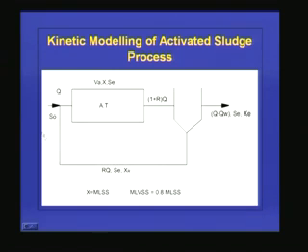solids, because sometimes along with the wastewater, the solids, along with organic solids, inorganic solids also will be there. So, this MLSS will be containing organic and inorganic solids, but if you want to find out what is exactly the microbial concentration, then we have to go for MLVSS, and many studies have shown that the ratio of MLSS and MLVSS is like this. If you have the MLSS value, if you multiply by 0.8, that is MLVSS, or in the total MLSS around 80% is MLVSS, that means volatile suspended solids or fresh cells.